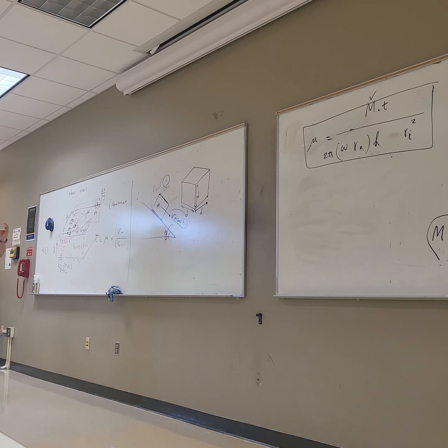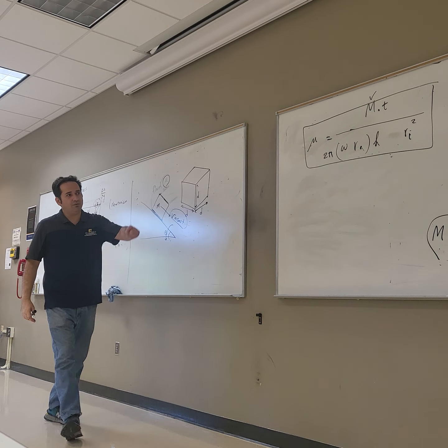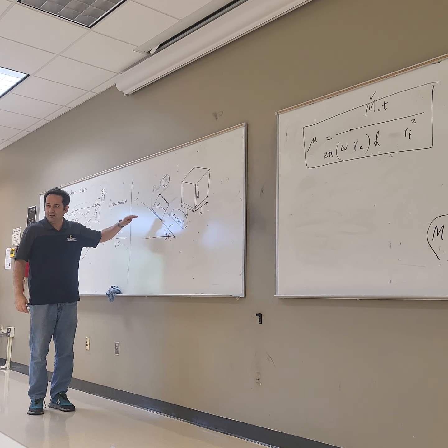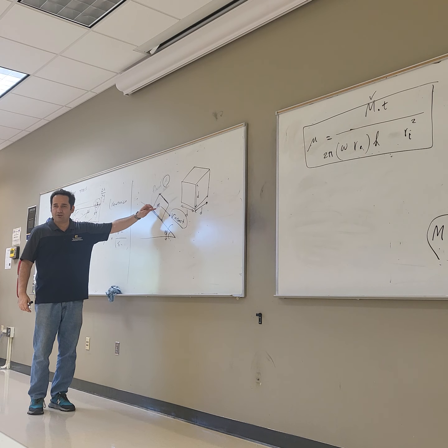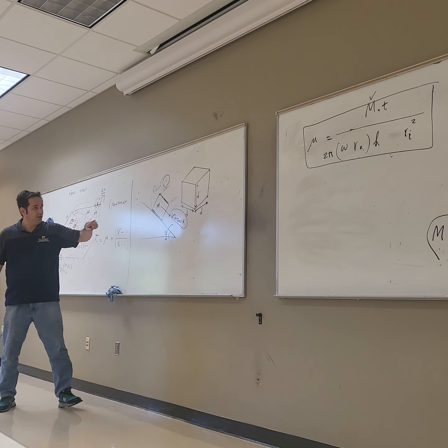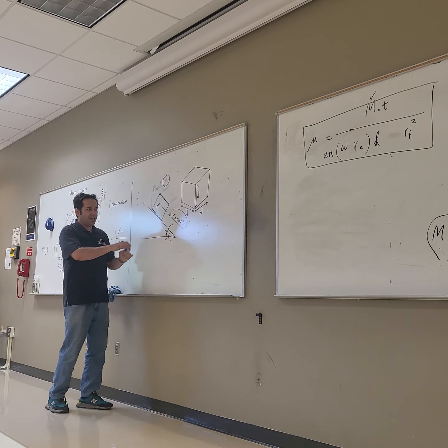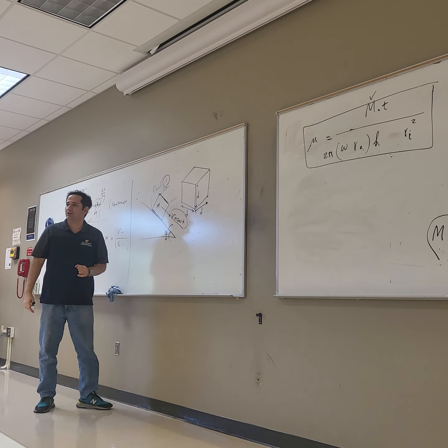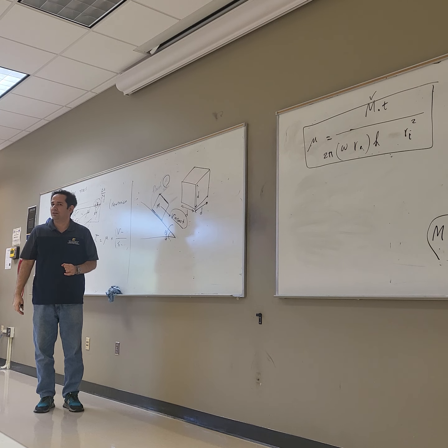You see, we are trying to find different ways of measuring viscosity. One way was the metal sheet, the other way was the cylinder. The other way is to make the incline, right? And then lubricate. This is not accurate. The most accurate one is that one. We are going to even make it more accurate. And then change the angle theta such that it goes down with constant velocity. Tan inverse theta.